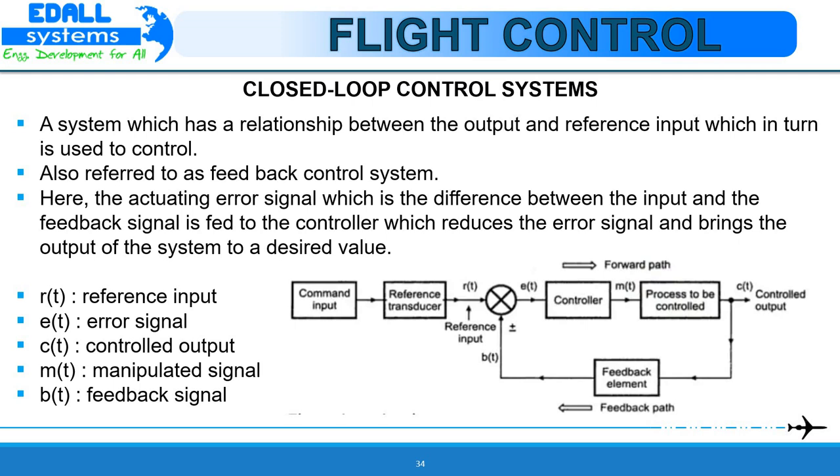Apart from this, there are a few disadvantages also, where such systems are complicated and time consuming from a design point of view, and also costlier. Due to the feedback, the system tries to correct the error from time to time. The tendency to overcorrect the error may cause oscillations without bound in the system. Hence, the system has to be designed taking into consideration problems of instability due to the feedback signal. The stability problems are severe and must be taken care of while designing the system.